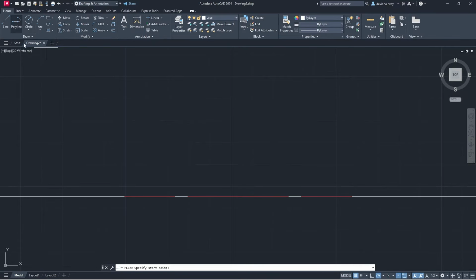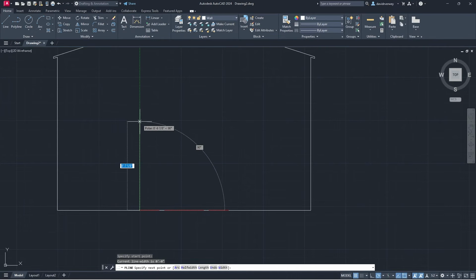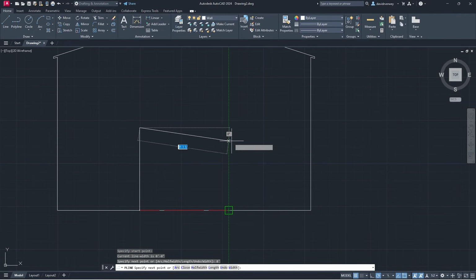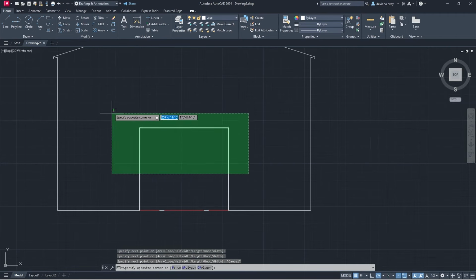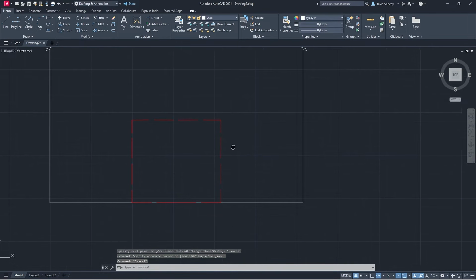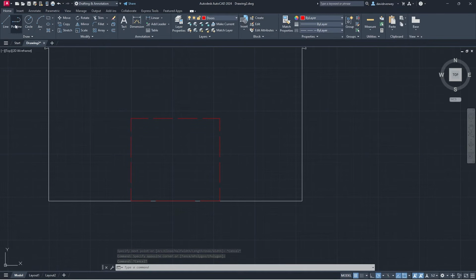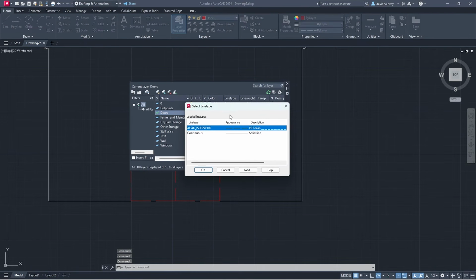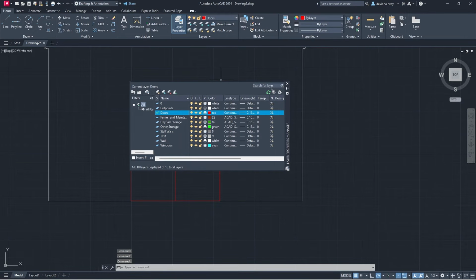I'm going to get my polyline, go to the corner of my door. My doors should probably be, let's do 8 feet. Line it up, put it down. My layer again did not switch. Doors, and that's our main door. We're gonna go door, polyline. I'm gonna go in the middle, just to show that. I'm actually gonna switch our door layer from the dotted line to just a solid line, just so it's easier to look at.